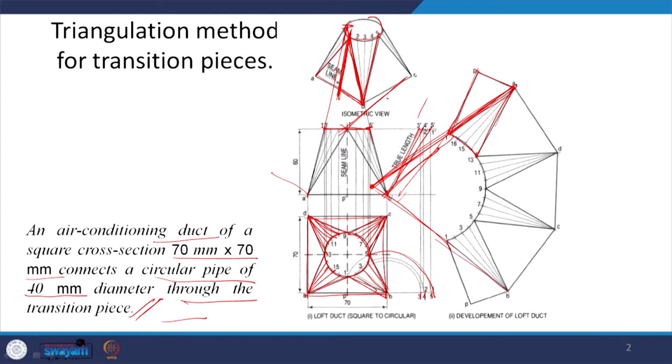This is the part which is actually getting cut, which we get from here, and this is the rest of the part, and the circumference of this circle is going to come here. So we again divide it into 12 equal parts. Only the top circle we divide into 12 equal parts, 4 parts for 4 filler parts. So we just connect to the 4th part. This is the part we get, and now we know that this is where the triangle is going to come.